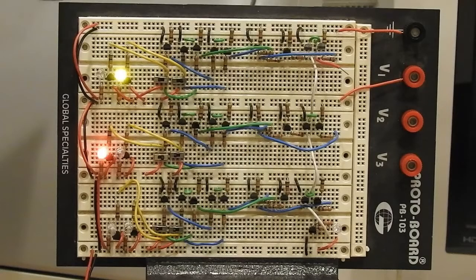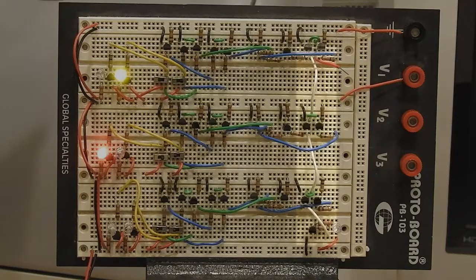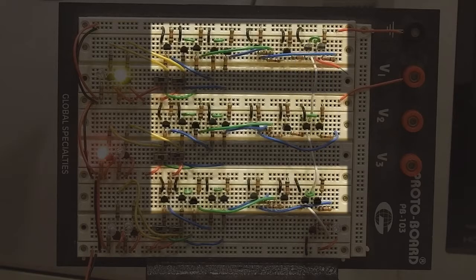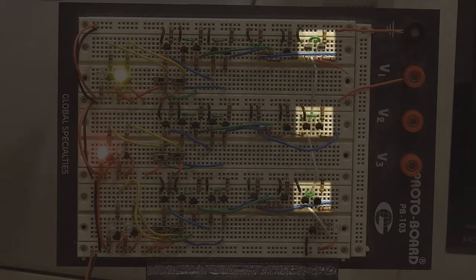Now I've taken the liberty to wire up the previous example on a breadboard using NPN transistors. This white wire represents the common wire of our bus. It connects all the way from the top to the bottom. And each row of transistors is our three-state gate. These are the transistors which drive the bus wire high or low.